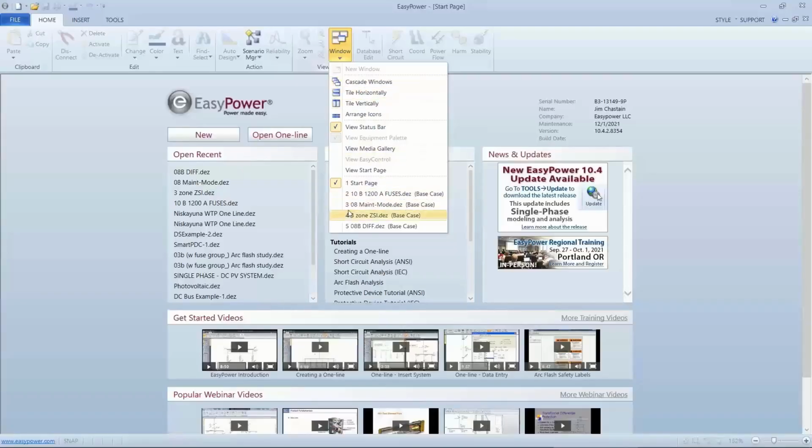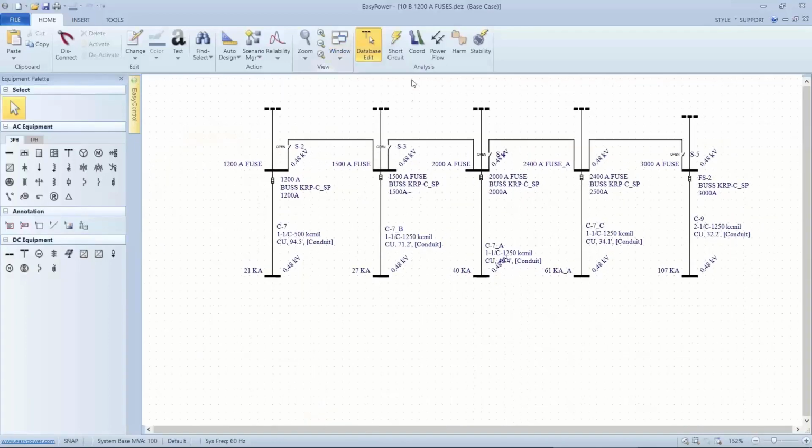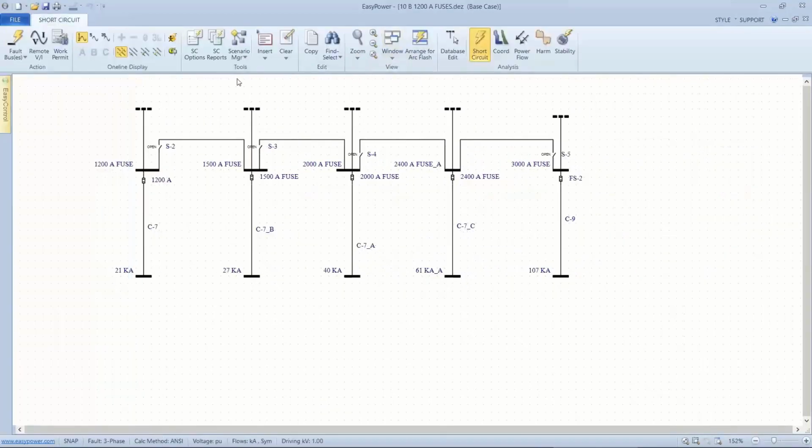What we're looking for is the incident energy due to the arcing current in that particular phase or supply. Right now we're looking at the total available bolted fault current, which includes the upstream supply and any motor loads connected downstream.